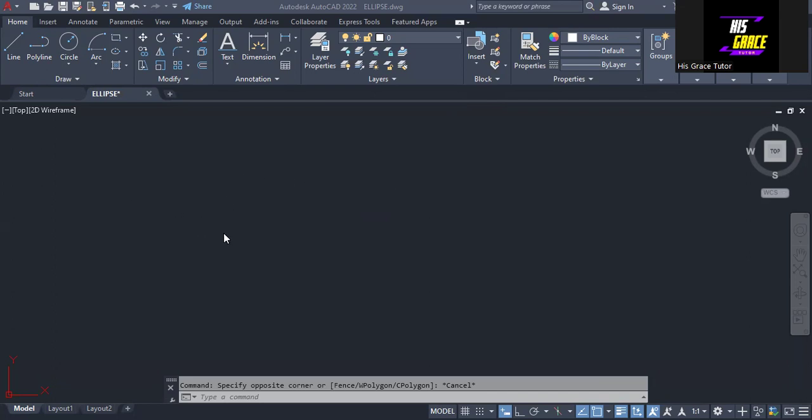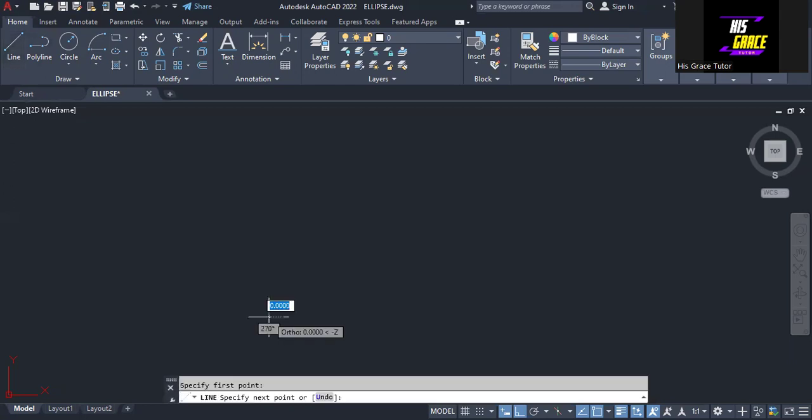So let's start. The length of the side of the pentagon is 20 millimeters, and we are going to start this way. We first of all need to activate the auto mode. So I've activated it. Then we come to line. Then we draw a line, and we are going to enter 20. Then press the enter key on the keyboard. Then we are going to deactivate the auto mode because we want to draw this side now.